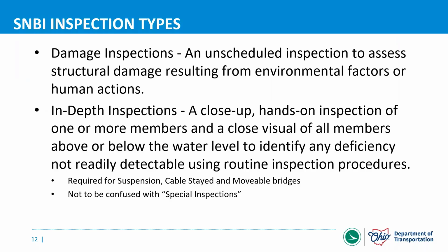We're choosing damage inspection type. And then, a lot of times, right, for a damage inspection, a critical finding is also being filled out. Not saying that it always has to be, but right, if the rating of the bridge is now coming down to a 2, or you're going to restrict, on top or on bottom, during the damage inspection, then we want that critical finding form filled out.